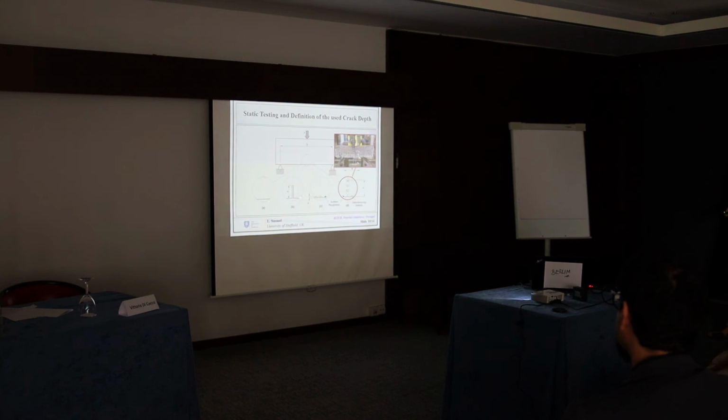So while when we were manufacturing the conventional or a crack-like notch, it was easy for us to define the crack length. We also decided to define a crack length to model the superficial roughness. So basically the idea was we treated these little valleys as local small cracks.